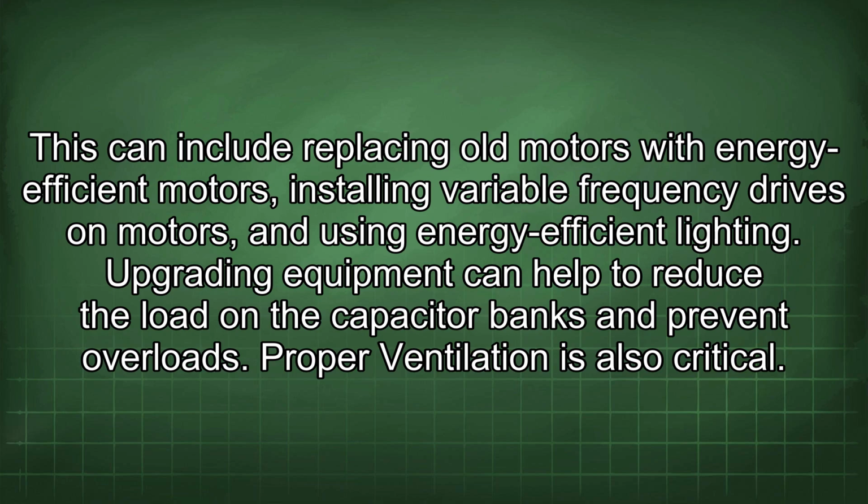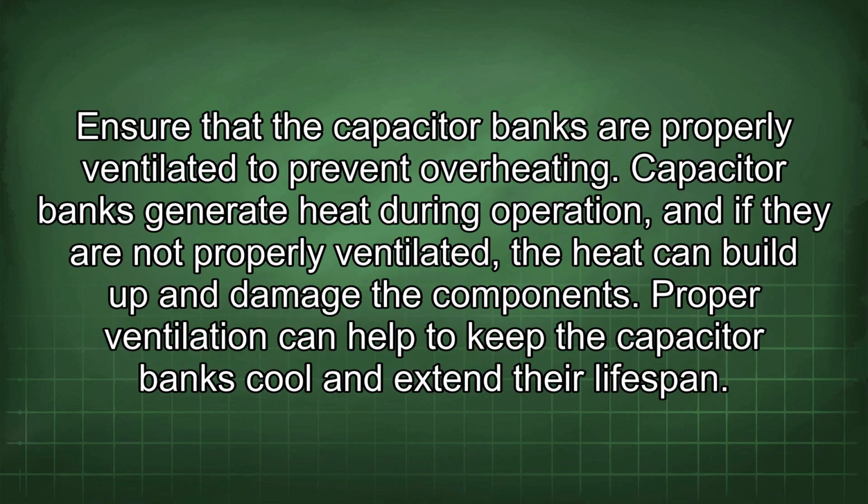Proper ventilation is also critical. Ensure that the capacitor banks are properly ventilated to prevent overheating. Capacitor banks generate heat during operation, and if they are not properly ventilated, the heat can build up and damage the components. Proper ventilation can help to keep the capacitor banks cool and extend their lifespan.